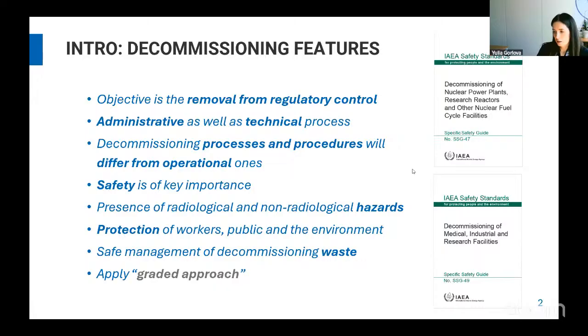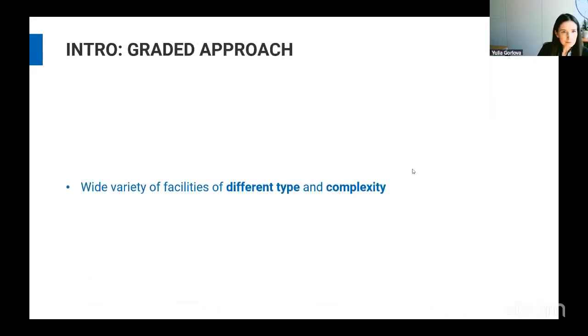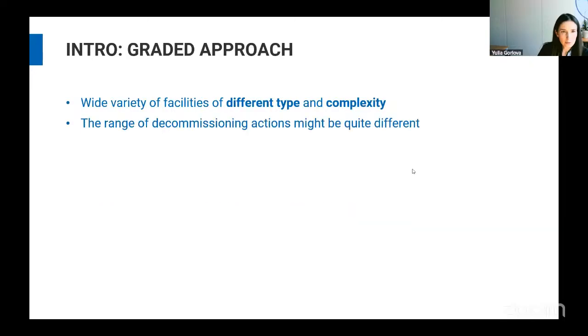That means that the actions, planning, documents, scrutiny from the regulator, and the planning and implementation actions from the licensee should be commensurate with the present or expected hazards, with the complexity of the facility itself, and with the complexity of the actions and activities during decommissioning that need to be implemented to reach the end state and to get the decommissioning license terminated. So, this is about the graded approach.